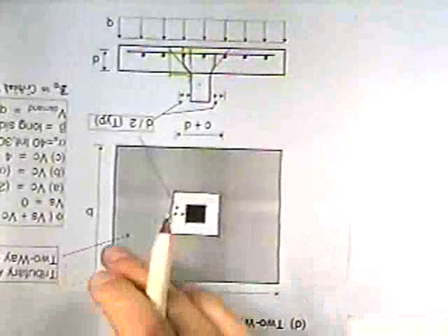The phenomenon is that there's bending in 2 directions, whereas in the first case it was only in one because the whole part just sheared right off. But now we're getting shear that goes all the way around. So the mechanism's different. A lot of the stuff in the code in the concrete part, some of it doesn't make sense, and you say, where the hell does this number come from? But it comes basically from a lot of experimental tests. Same thing goes for development length. Where do you get these formulas from? It's just from matching experimental data.